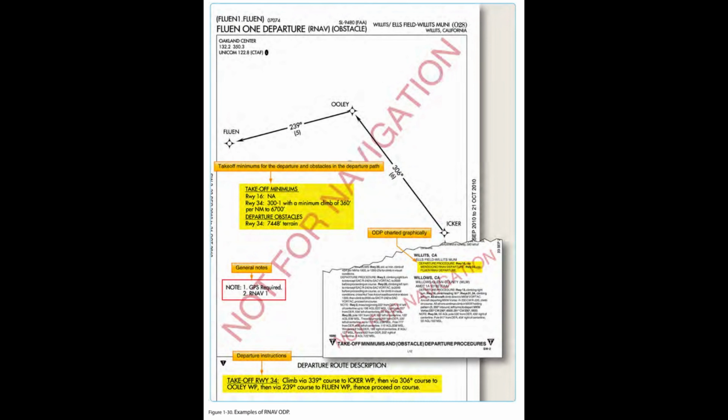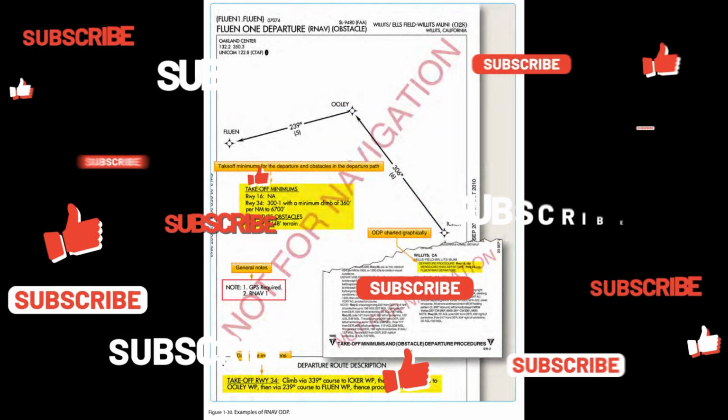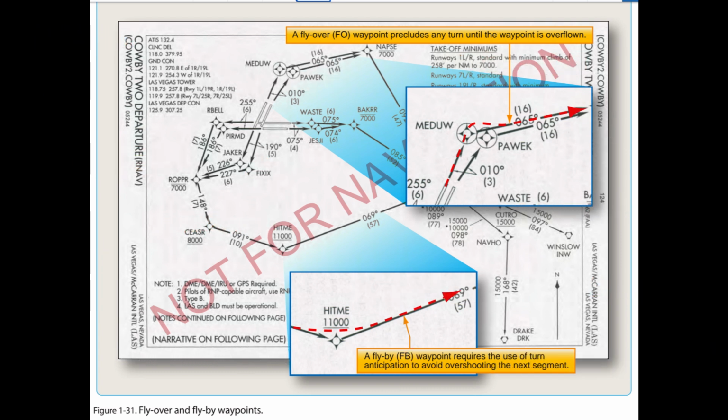Additionally, new waypoint symbols are used in conjunction with RNAV charts. There are two types of waypoints currently in use: flyby (FB) and flyover (FO). A FB waypoint typically is used in a position at which a change in the course of procedure occurs. Charts represent them with four-pointed stars. This type of waypoint is designed to allow you to anticipate and begin your turn prior to reaching the waypoint, thus providing smoother transitions. Conversely, RNAV charts show a FO waypoint as a four-pointed star enclosed in a circle.